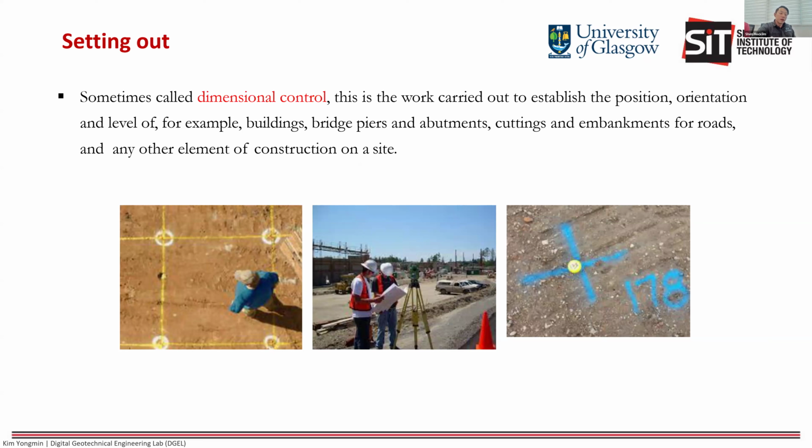And surveyors mark physical points on the construction site. It can range from pile caps to the center median of the road, the edge of the drain. And it's very important at this stage that you be as accurate as you can, because accuracy here basically determines the construction quality. And I would like to add that at Hocklim, the surveyors communicate constantly with the site supervisors, and you need to maintain your engineering survey tolerances. Setting out is where your design actually gets translated onto the ground. This is the part where you get all your irregularities and you start to resolve the conflicts.